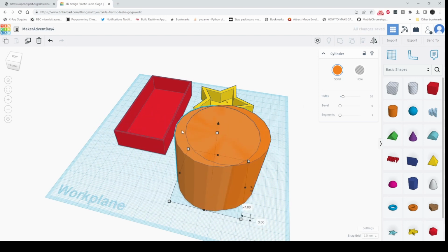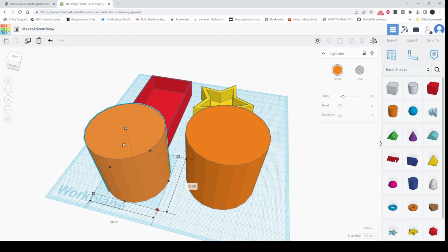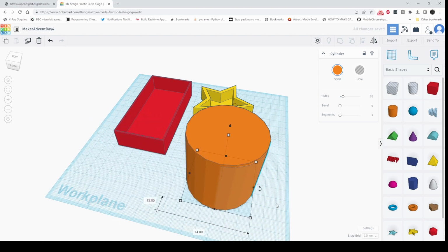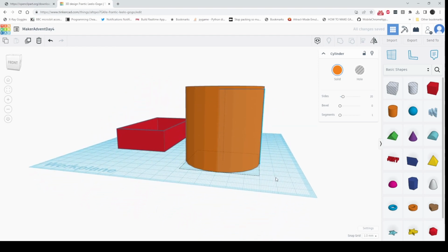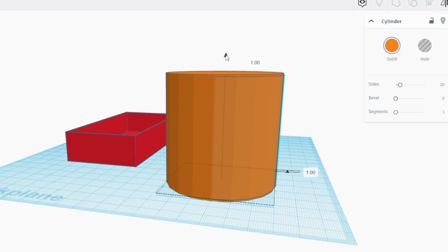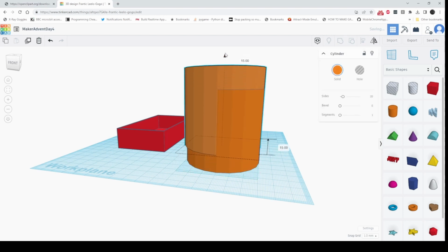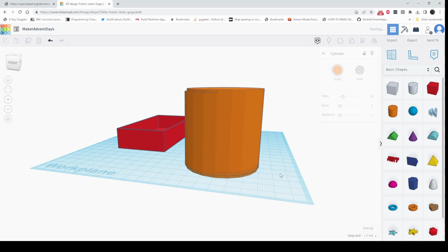Well, yes. But we're going to change the diameter of this to be, let's see, it's 60 now. Let's give it a 2mm wall. So let's do it to 58mm. There we go. Let's put it inside. Okay, you can't see anything yet because I've not done anything. It's just inside, isn't it? Let's raise it up by 2mm. I'm using a little cone here, which will move it up and down. I'll click on it again, and there you go. It's like an elevator.